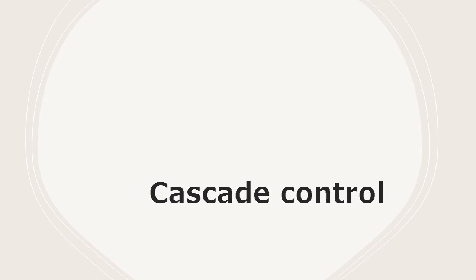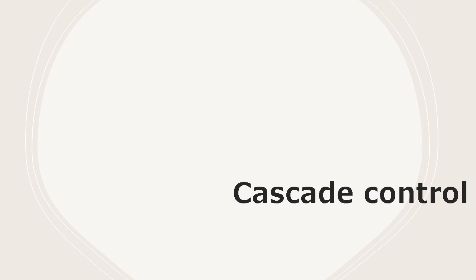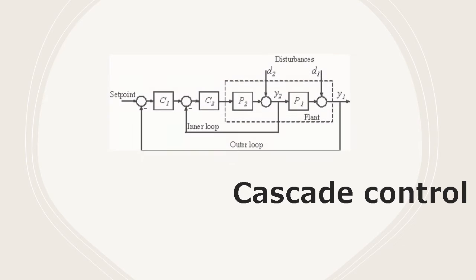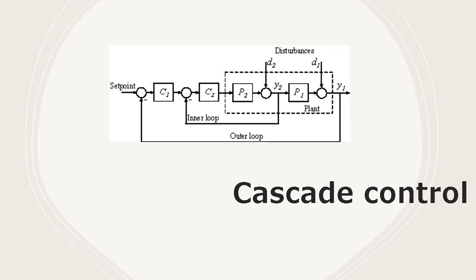Cascade control is a variety of single-loop PID or PI control arrangement in which two or more controllers are connected one inside the other, in such a way that the disturbance is minimized by feeding the output of the first one to the following one as a set point. This configuration allows the disturbances to be attended simultaneously at different points of the plant.